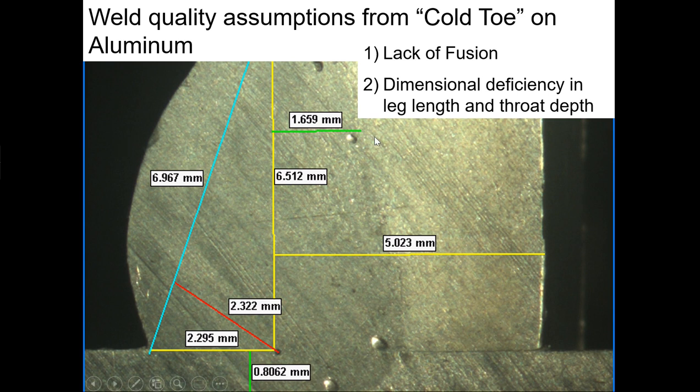Here's a cross section that was put in place, and I brought it out because it has a cold area in here. This is the condition I was talking about from a visual perspective. When you see a weld that rolls back like this, that should set off warning bells that this area requires some attention, this area right down in here. Because if you're getting this rolling back, your heat input here is very low.